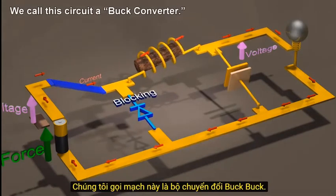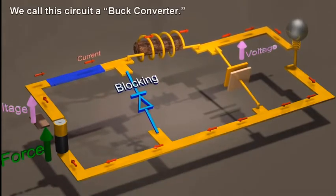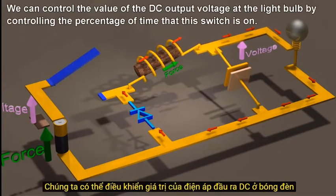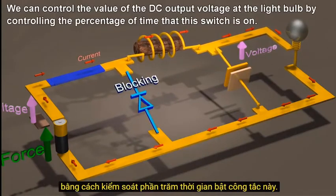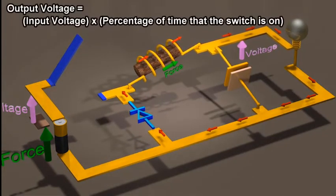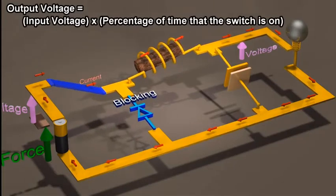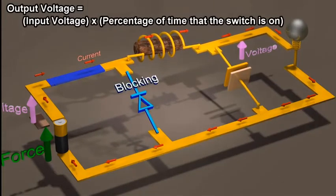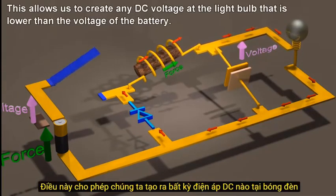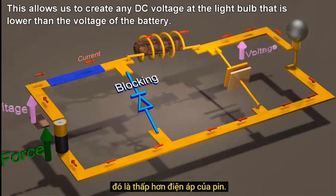We call this circuit a buck converter. We can control the value of the DC output voltage at the light bulb by controlling the percentage of time that this switch is on. This allows us to create any DC voltage at the light bulb that is lower than the voltage of the battery.